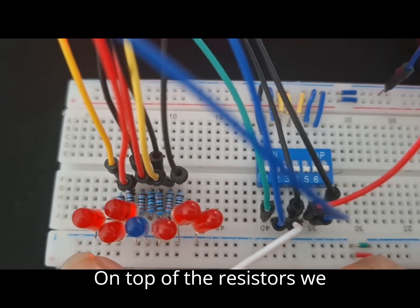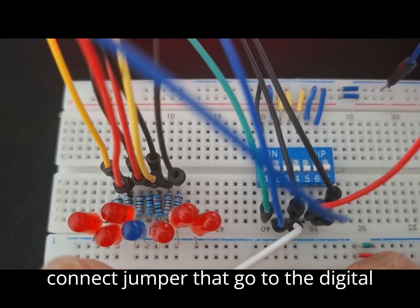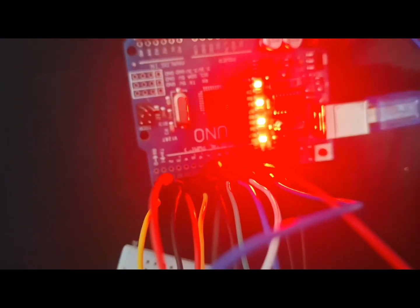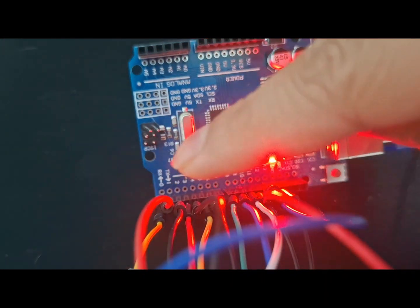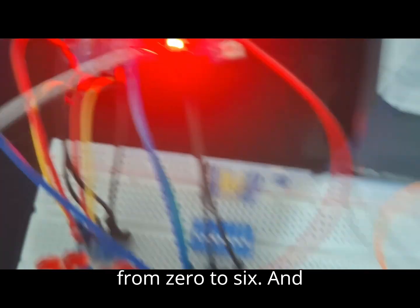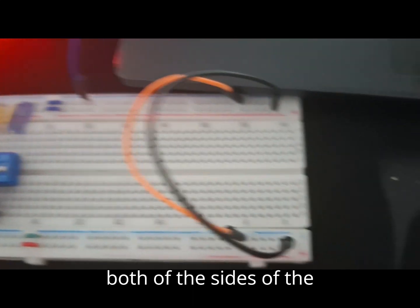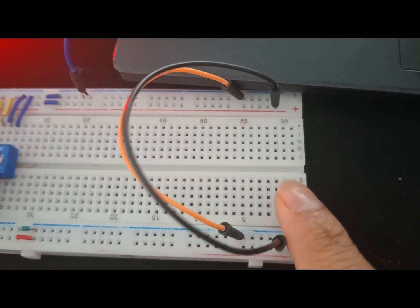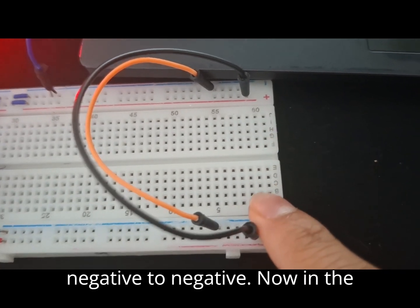On top of the resistors, we connect jumpers that go to the digital pins of the Arduino, from 0 to 6. And we also have the jumpers that connect both sides of the protoboard, positive to positive and negative to negative.